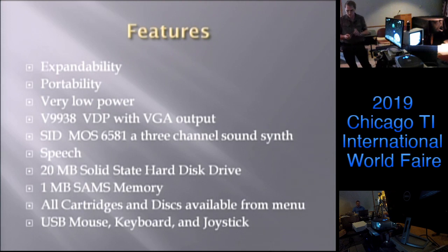The other thing with this interface, so the first board that I intend to make that will be an expansion board for this will have a serial port and a parallel port on it with all the handshake lines. Additionally, it will have several connectors that you can plug cartridges into that will be 3.3 volts.